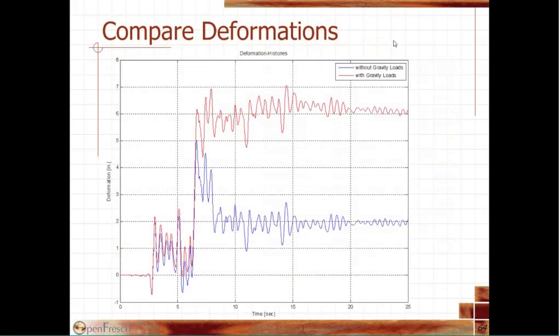And once we put gravity loads on and we start capturing the second order effects, you can see how the example actually starts collapsing. Somewhere between 6 and 7 seconds here, deformations get really big in the case where we have the gravity loads on our portal frame, and through each cycle they tend to get bigger, so really that is actually collapsing there.